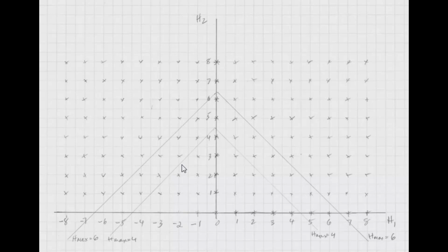So if you are doing a problem where you want, say, 3F2 minus 2F1, you better have quite a bit more than 3 and 2 harmonics of those two respectively. And that has to do with the way the two-tone Fourier transforms work. I don't really want to say much more of it beyond that, but you do have to be careful.